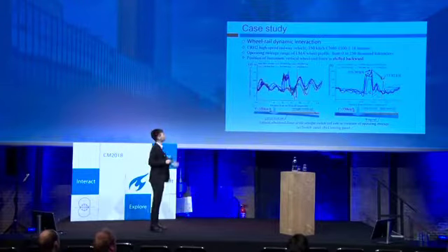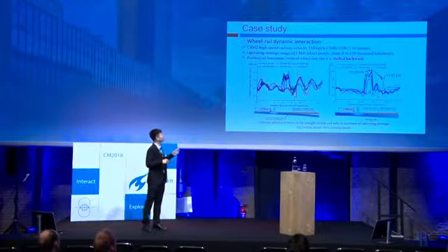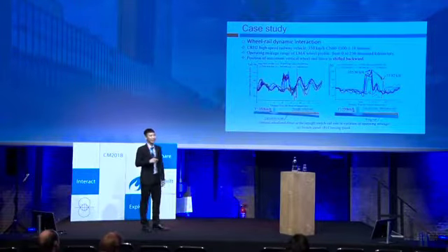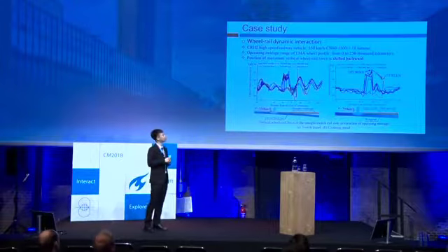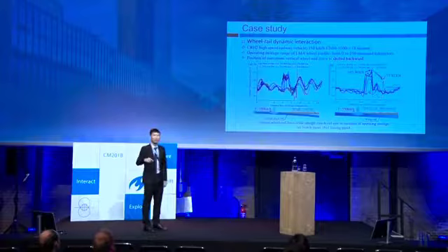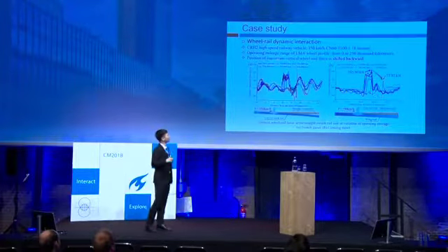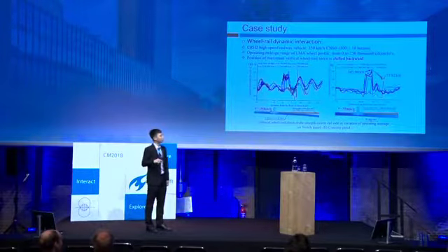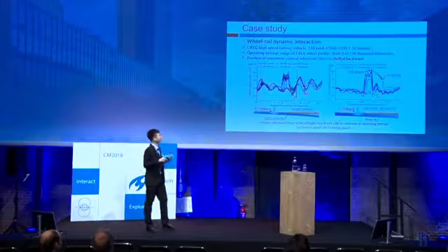Now we will move on to the case study, and we consider the wheel profile evolution. As shown in this figure, the simulation of a vehicle passing through the turnout in the straight route of the facing route at a speed of 350 kilometers per hour is carried out. And it is found that with the profile evolution, the maximum vertical wheel-rail force decreases from 106 kilonewtons to 78 kilonewtons. And the position of the maximum vertical force is shifted backward.